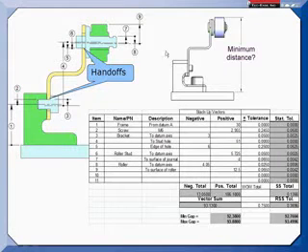If we look at our tolerance analysis for this, to get the minimum distance, I push the roller down against that surface. I push the stud down as far as it would go. I push the bracket down against the screw.